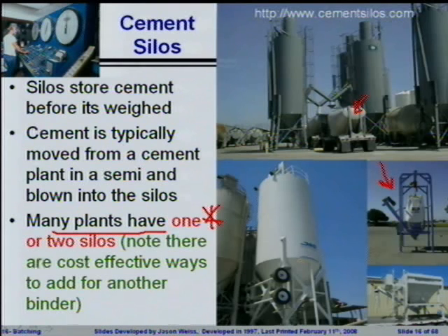The big problem there is down the road, the concrete has been produced, and you thought you had a mix that had 20% fly ash. It actually has 20% cement. And now you've got a quarter mile of it placed. And what do you start to do about the problem?